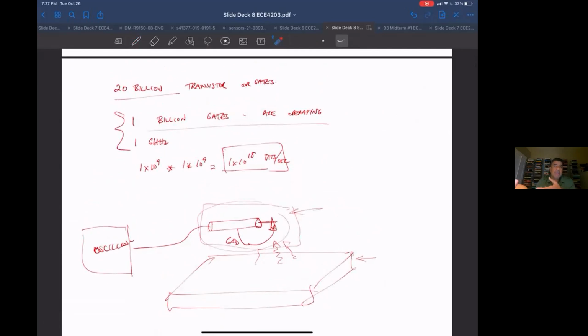And the reason you usually don't build in error correction is because there's a big overhead of circuitry and a big overhead of time. There are places in your chip or in your FPGA that you do typically put in error correction, and those are in your high-speed serial inputs and outputs coming out of the chip. You might have it in your DDR memory access, things like that, which are very specific communication circuits in and out of your chip. But typically your stuff inside the chip, like if you're accessing memory inside the chip or doing some calculation, will not have any of that.